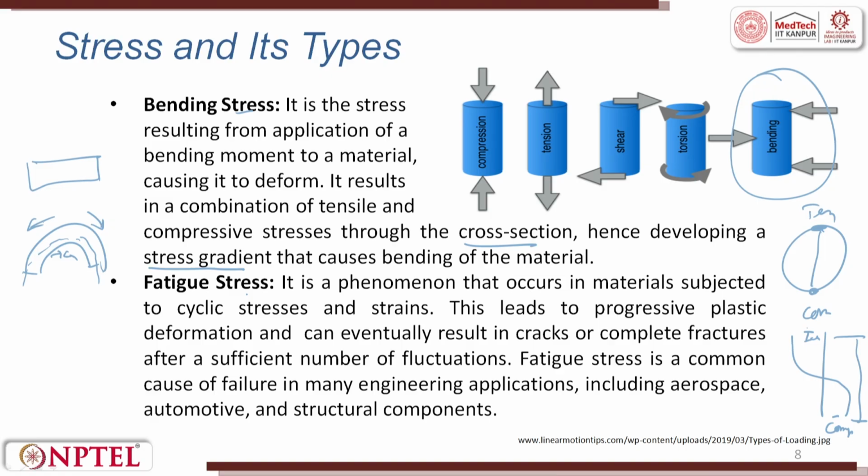Fatigue stress is a phenomenon that occurs in materials subjected to cyclic stress and strain. This leads to progressive plastic deformation and can eventually result in cracks or complete fracture after a sufficient number of fluctuations. I keep on doing on and off, on and off like this. After some point of time, you will see that this material gives way.